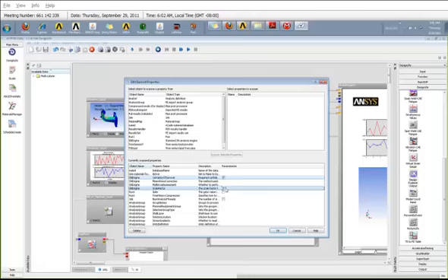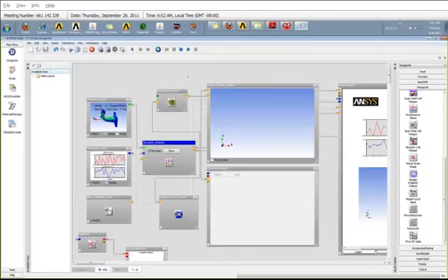The scale factor actually applies a scale factor to the stresses before the fatigue calculations. And the certainty of survival allows statistical variations in the material behavior to be taken into account. The usual application of this is to provide a more conservative prediction to ensure a safer design. So these are some of the input parameters that I can set.